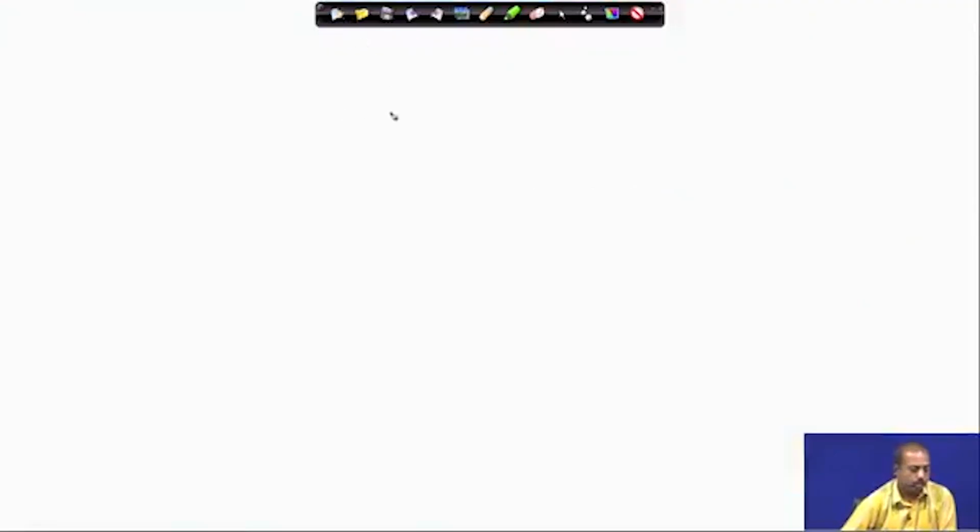So, first we configure this TMOD register. So, MOV TMOD, #20H. What will it do? It will set this TMOD register, so that it is basically the auto reload mode and the other settings, so that it will be operating in this mode of operation. So, it can be used for the serial transmission.